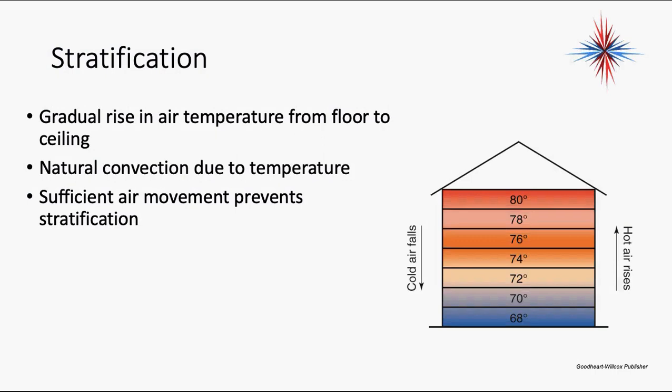When we're designing ductwork and vents, we look at the average HVAC use in the area, and that's where we put our return and supply vents. The further south you go, the return vents are mostly on the ceilings, as well as the supplies, because of that stratification. We want to get the heat off the ceilings. The further north you go, a lot of times this is all on the floor.